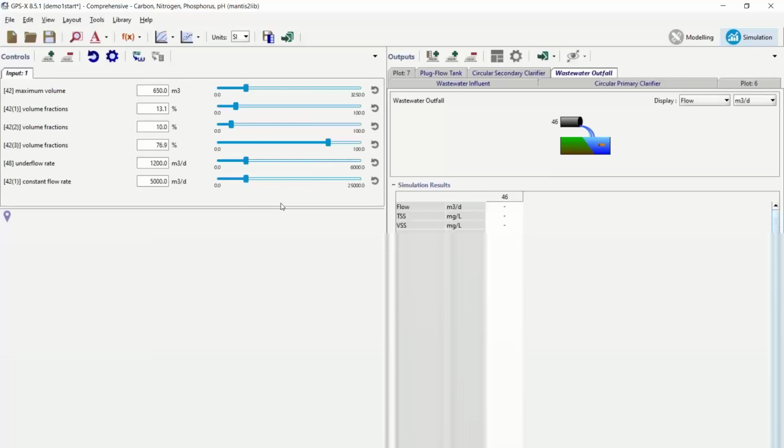It has the same connection points as the regular one, except an extra one up here called influent number 2. It's not really an influent, it's where you put in the chemical for this. So it would look like this when you were to lay it out. This object here is our COD chemical dosage object. It's found in the influent tab. And so you would put that down here. And if you right click and open up the chemicals, you can see the various types of carbon addition that you can do, like methanol or glycerol, or mixed substrate is for things like micro C, the synthetic stuff.